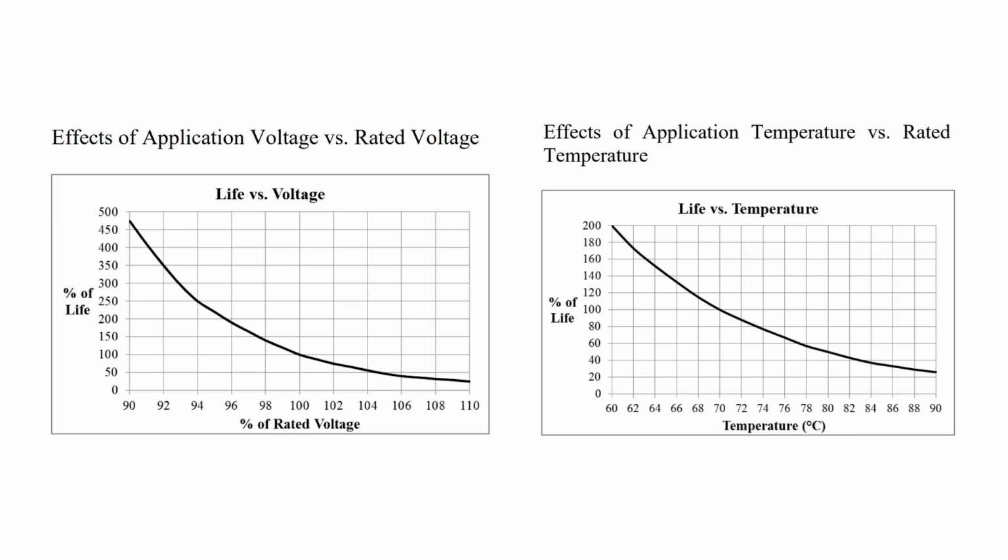A couple things that I want you to know about these run capacitors and how they're tested. They're tested to last for 60,000 running hours. It's not cycles, because in a run capacitor, they're in all the time. There are no real cycles. The unit goes on and off, but you're cycling 60 times per second anyway. Your voltage, your sine wave, is going up and down 60 times per second anyway, so turning it on and off isn't the issue. It's how many running hours it runs. And 60,000 hours is a long time.